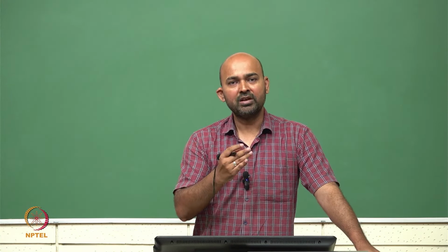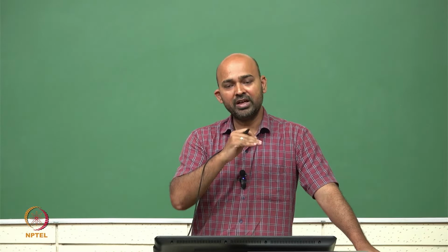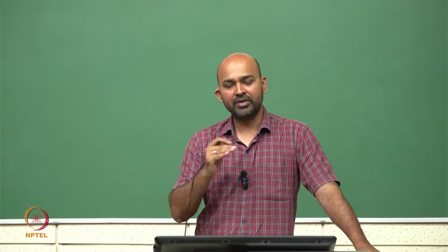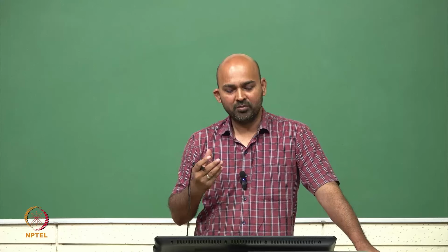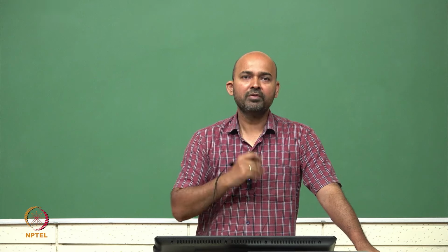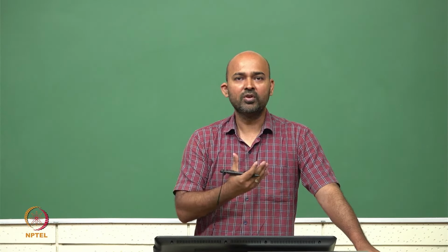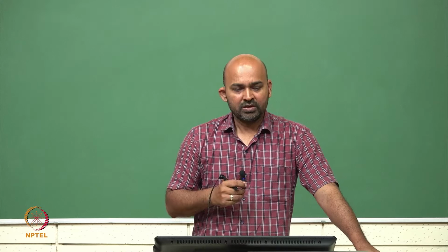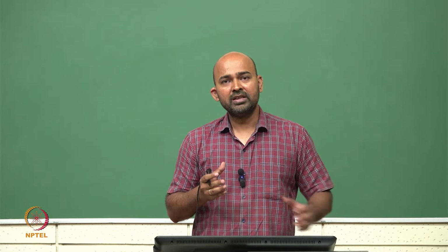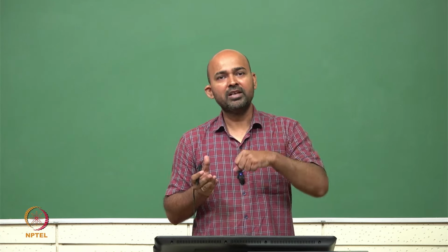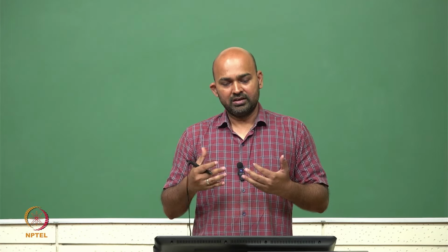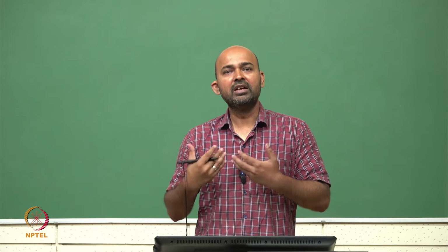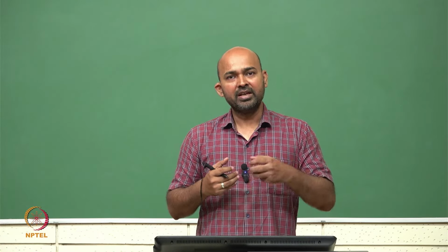from this device. So, we are not particularly interested in on and off, but in the transition region where the MOSFET is turning on, and during turning on, how much gain the MOSFET has. That is typically for analog applications, and on-off, where we are using it as a switch, is used for digital IC design. This MOSFET is nothing but a voltage control device where we apply a voltage and change the transconductance, or the capability of driving current. So, that we can change by applying a voltage.